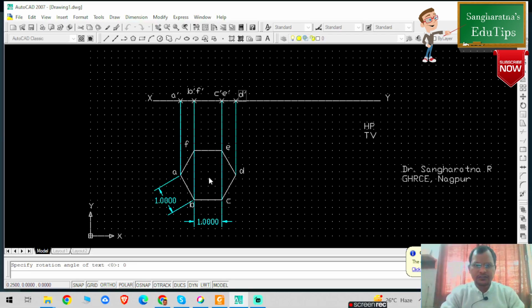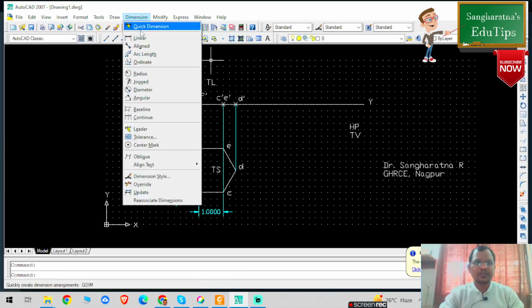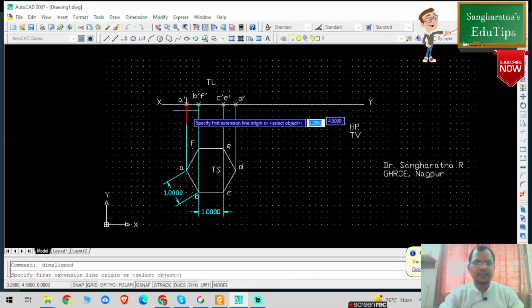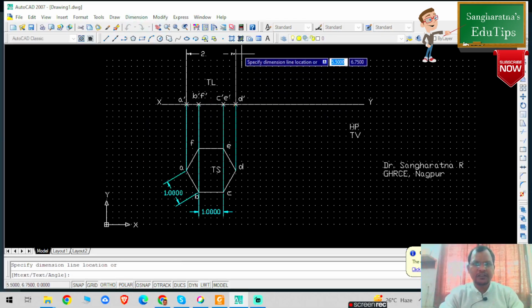Okay, so this is basically my true shape of the hexagonal plane, and this is my true length. Okay, so I'm clicking on the outside, then press escape. Now I need to know the dimensions of this particular true length. So I'm going into the dimensions, click on the align. Okay, selecting this particular point, this particular point. So you can check, this is basically 2 AutoCAD unit, that means 200 mm.